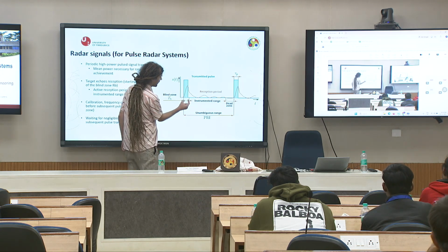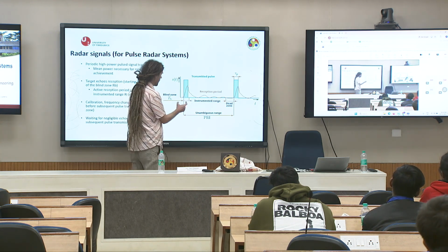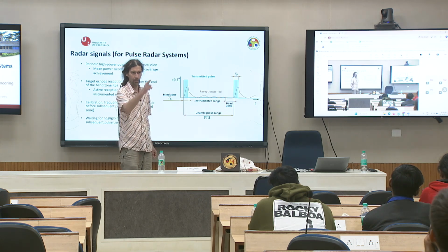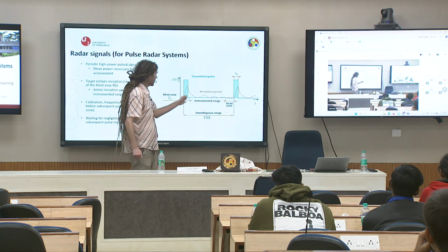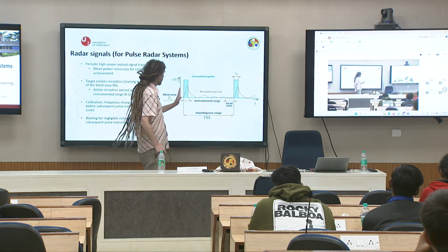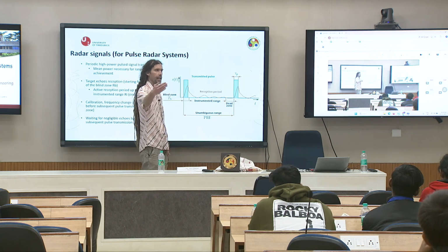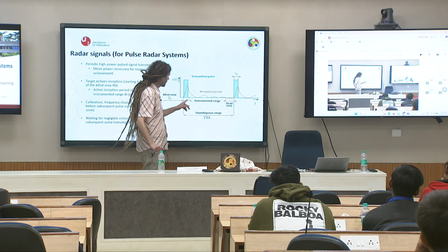There you can see the length of the pulse plus some amount of time, we call it the blind zone. This is the blind zone that I already presented in this circle. It is the zone where, after I finish transmission, I can't receive any answer because the signal will be so strong that it will destroy my receiver. Clear?